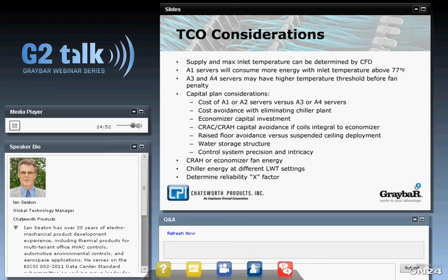If you can't get that information from your server manufacturer, you can get it from charts in the ASHRAE handbook, and those charts, by the way, were developed by the server manufacturers, so that's defensible and accurate enough for planning purpose type information.